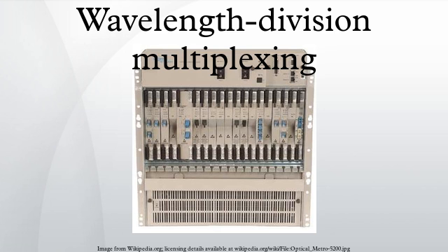The relaxed optical frequency stabilization requirements allow the associated costs of CWDM to approach those of non-WDM optical components. CWDM is also being used in cable television networks, where different wavelengths are used for the downstream and upstream signals. In these systems, the wavelengths used are often widely separated. For example, the downstream signal might be at 1310 nm while the upstream signal is at 1550 nm.